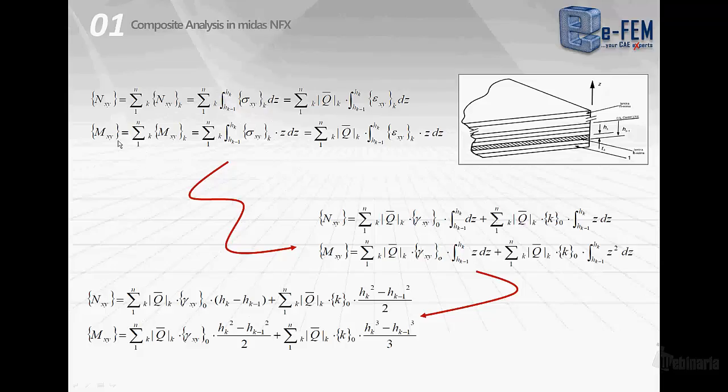If we then explode the term that gives the N and the M load components, we can integrate partially onto each lamina what happened to the complete thickness of the laminate. So we can divide the integration through the entire thickness of the laminate as the sum of the single integrations onto each lamina thickness. Just substituting the formulas, the matricial form for the single laminas that links stress to strains, we arrive at these final terms where the N and M components are expressed in terms of what happens in terms of deformation onto the single laminas.